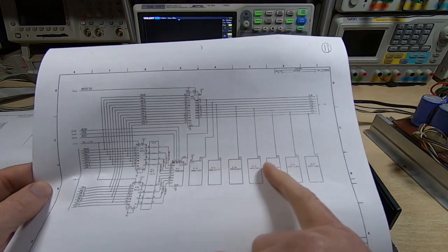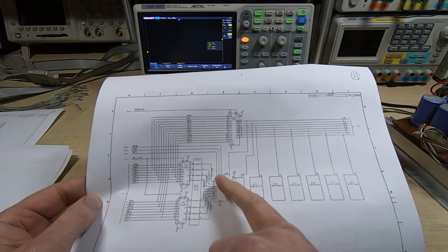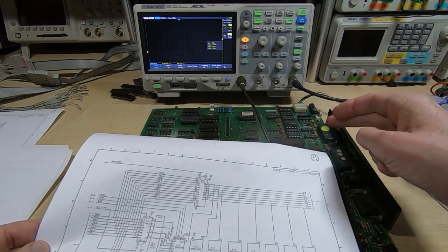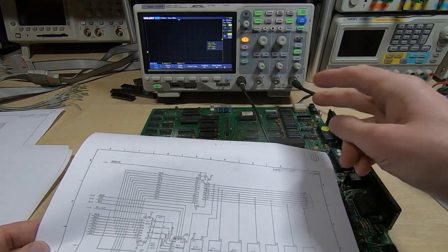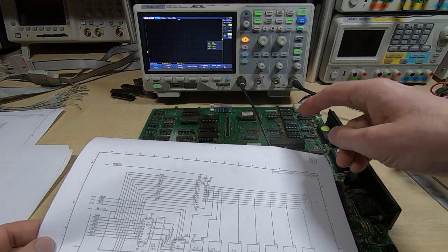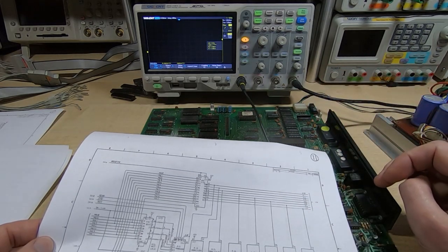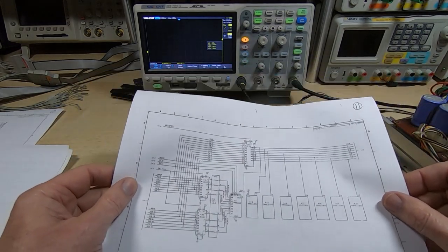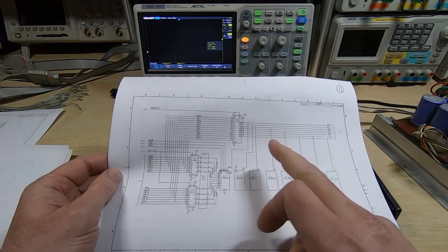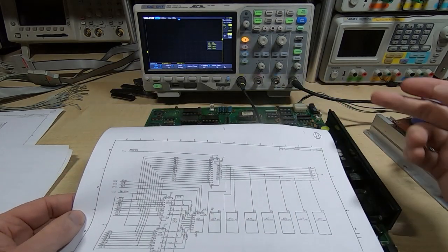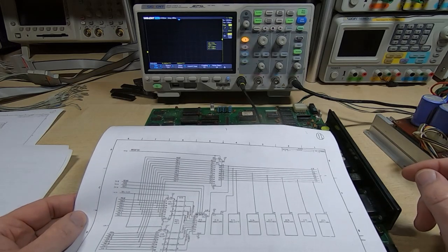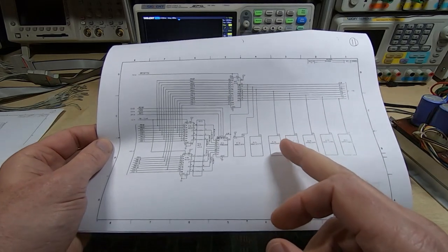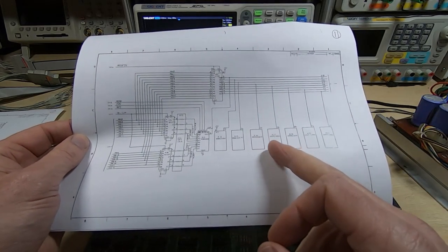So these are our DRAMs. Quite a simple arrangement. Now of course we do have to deal with the strobing of the DRAMs and the two-step addressing. If you're not familiar with that, then if you watch my series on the Z80 computer design, I do go into driving DRAMs in quite a lot of detail. But here the clue is that we're always getting a 0 back. It's not a kind of random value or a stuck bit or something like that. It's always 0. And normally that means that the DRAMs are not being put into the mode where they're outputting data.